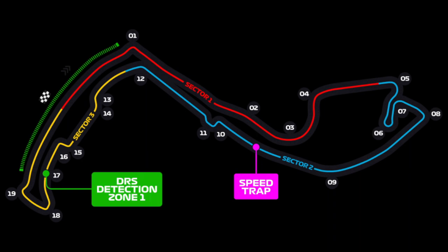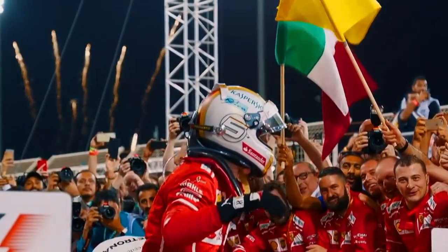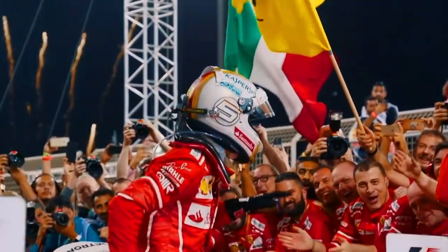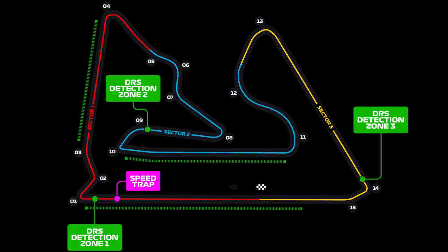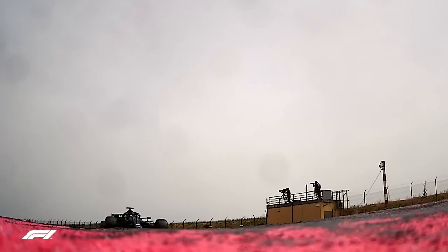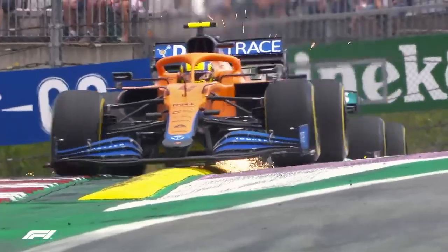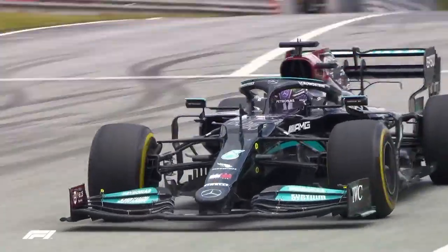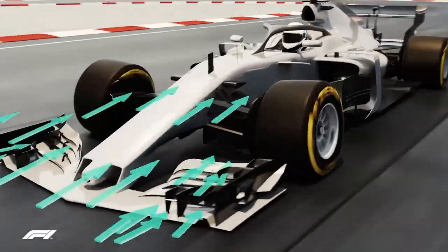Take the Monaco track, for example. There are minimal straights and several corners. Therefore, the F1 teams may change the aerodynamics of their car to generate more downforce. On the contrary, on a track like Bahrain, there are more and longer straights, and the generated downforce of the cars may be lower. However, this downforce comes at a cost, which is drag.